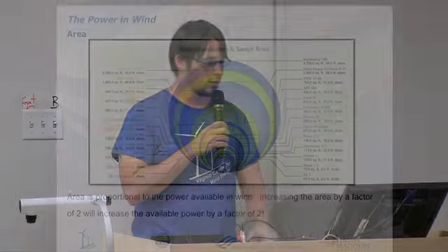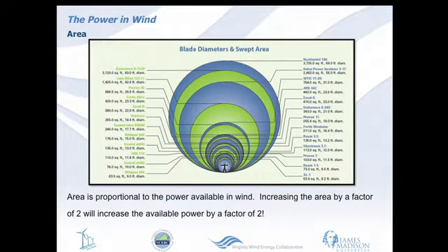And 20 kilowatts is even pushing it. Because as you go up in nameplate capacity, as was illustrated in a slide here, this image basically is showing you the rotor diameters of various different turbines. The biggest circle there is a 100 kilowatt turbine, and that has a 70-foot rotor diameter, whereas your 1 kilowatt turbine at the very bottom has an 8.2-foot rotor diameter. So as you go up in nameplate capacity on these turbines, your size grows quite large quite fast.